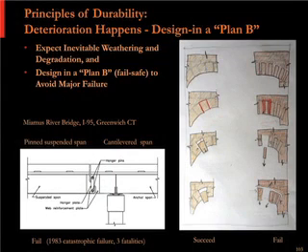The photo at the lower right is actually on Blue Hill Ave here in Boston, and those bricks just fell out of that arch. And the contractor was telling me he had never seen that in 20 years. And what they had there was a very wide mortar joint. They had a brick that wasn't wedge-shaped, so when the mortar eroded, the brick just slipped right out. And that's also what you see diagrammed on the center sketch on the right-hand side.